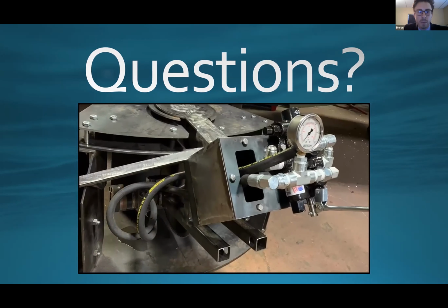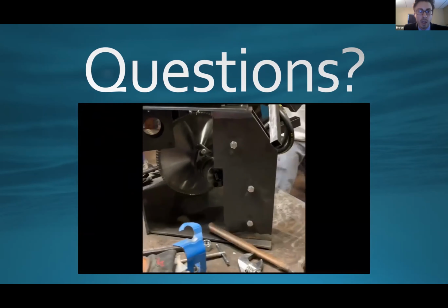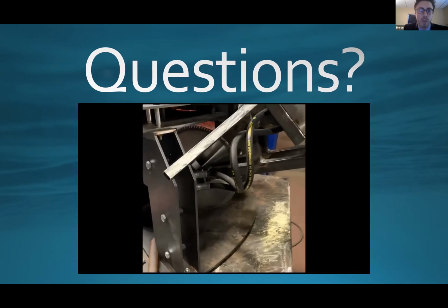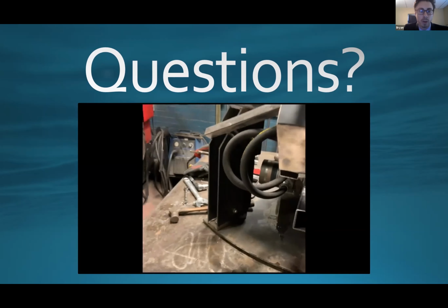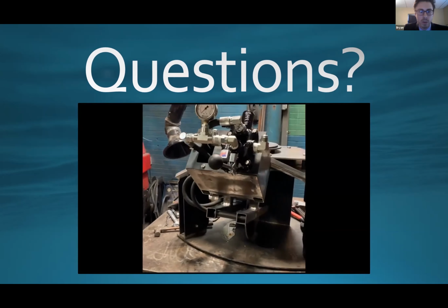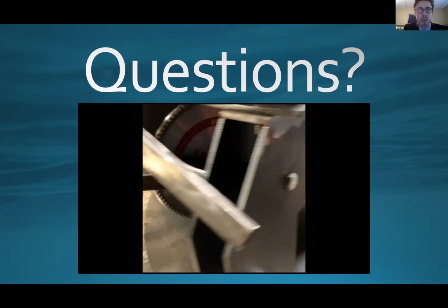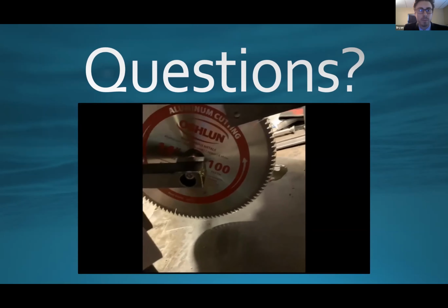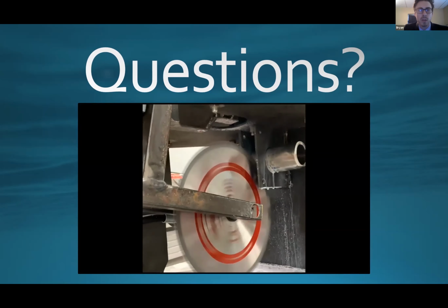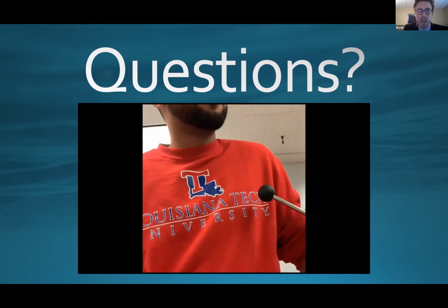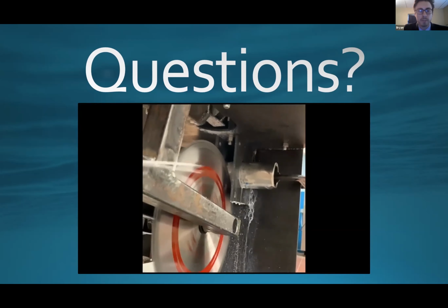The other thing we had to keep in mind was to not build any pressure vessels on accident. So all of those handles or pieces of tubing couldn't be capped in any way, because if they were sealed, they would just crush as you got deeper. And then, with salt water, of course, we're using carbon steel, so we'd have to do either some sort of cladding or protective paint, which Schlumberger uses a lot of. So we relied pretty heavily on our contacts at Schlumberger to get advice on how to avoid things like that.